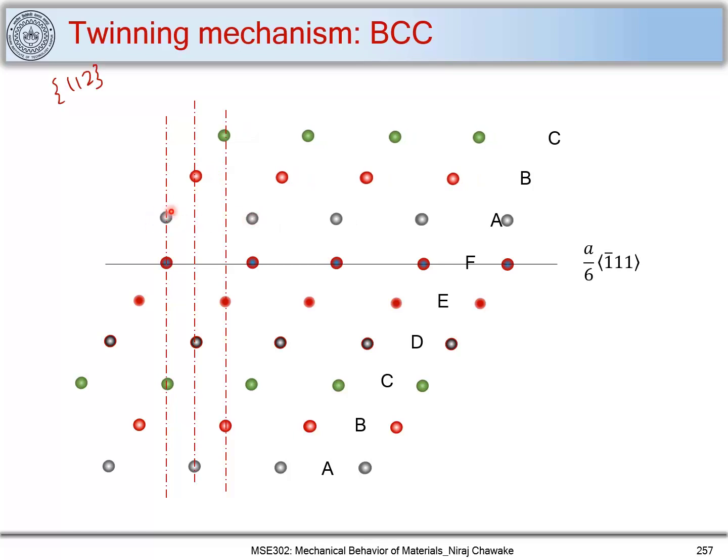You can see that these atoms are falling over each other, and thus this fault, or stacking fault, in the material will not be stable, and thus twinning in this direction becomes difficult. So when I moved these atomic layers in this direction, there is a creation of a high energy configuration, and that is not favorable, and thus this will not lead to any twinning.